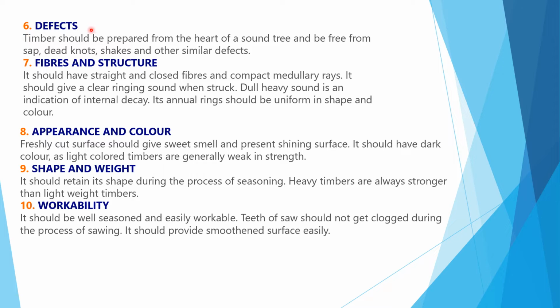Next, defects. Defects of timber. Timber should be prepared from the heart of a sound tree and be free from sap, dead knots, shakes, and other similar defects. Fibers and structure: it should have straight and close fibers and be compact.